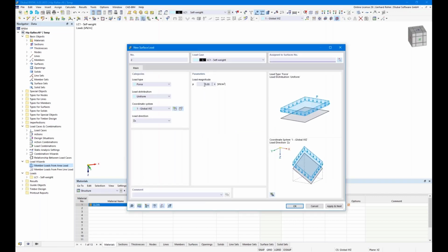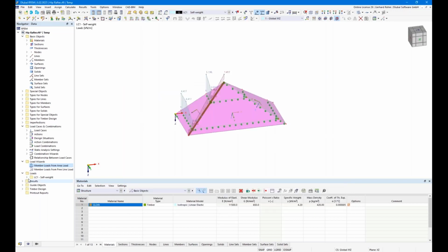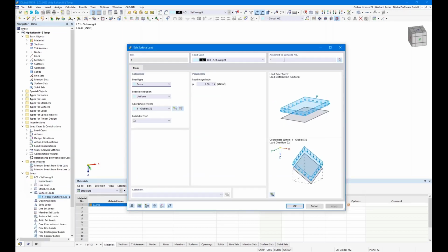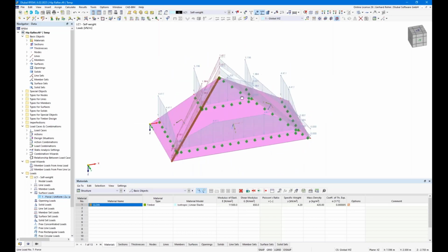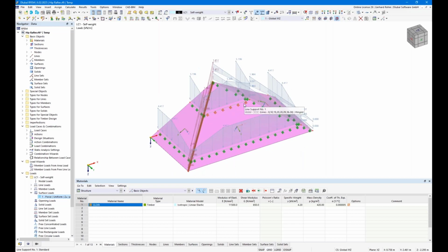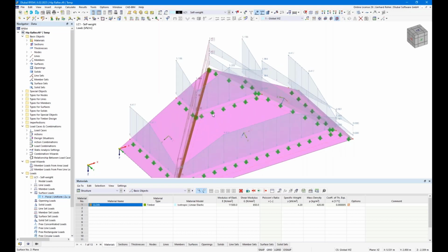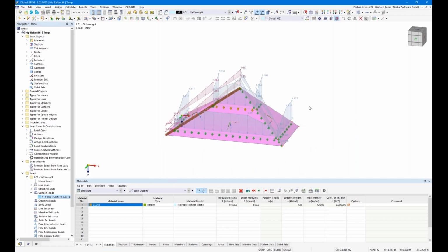Okay, and now we can apply the load. It's 1.5 kilonewton. I guess we have it already here. Just add 2 and 3. Yeah, and that's it. And the big advantage here is you will get directly the loads on this wall for the further design, or for example, for the purlin. Of course, you can delete the line hinge here and apply directly another beam and connect it with a hinge, for example, to consider the purlin. You can consider also a column underneath. That's also possible. But of course, for today's presentation, I will just focus on this hip rafter.